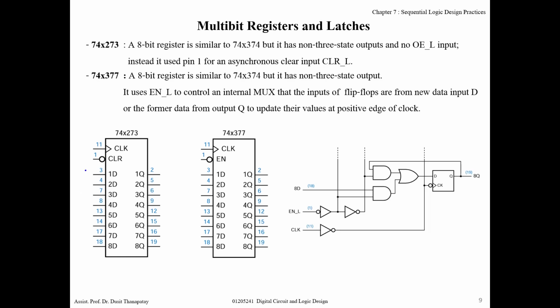This one has asynchronous clear. Namely, if you want to clear, it will clear suddenly. No need to wait for the clock tick. And this one has an enable, an enable control signal to make the flip-flop read data. This is also 8-bit, 8 flip-flops inside, but with a common enable.